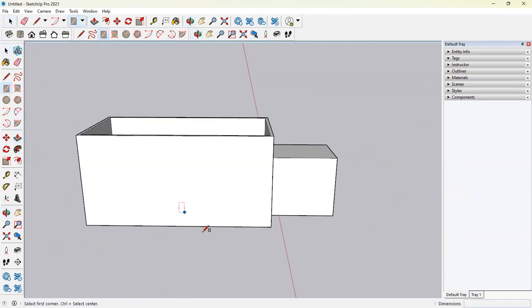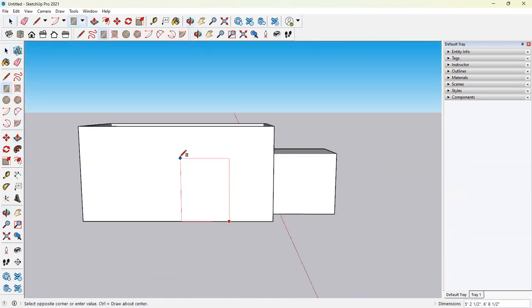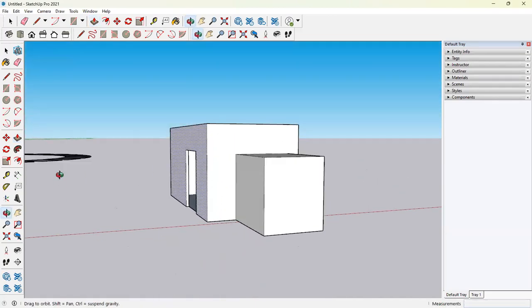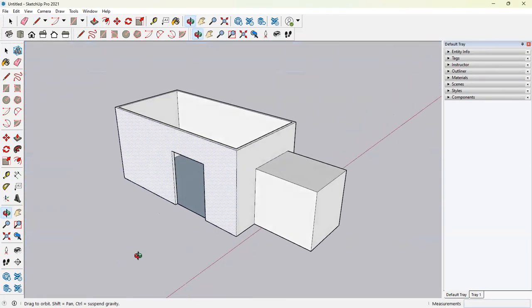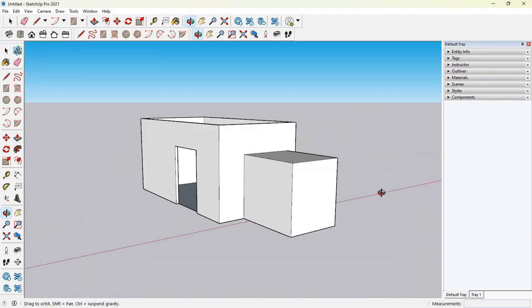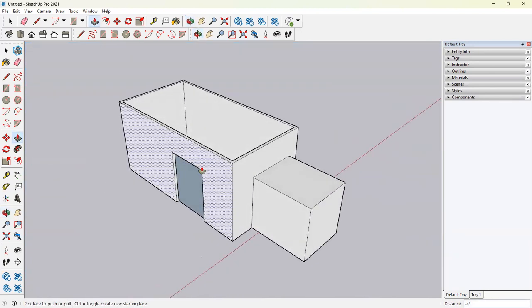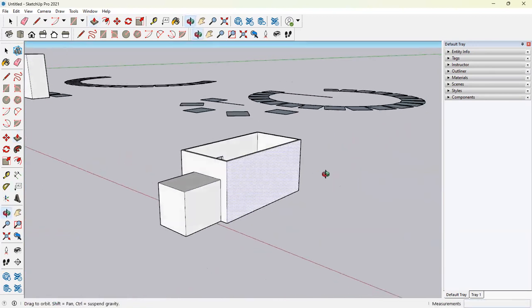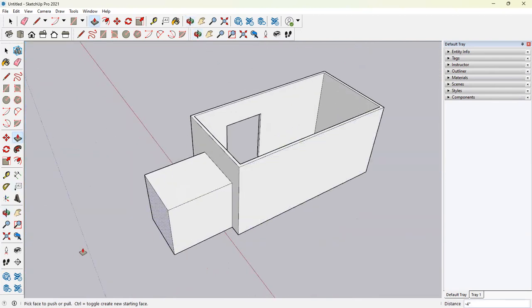Similarly, if I have a geometry here and I use push-pull, it's saying that its offset is limited to 4 inches because the thickness of our wall is 4 inches. So if you leave it, it will make a hole in the wall. So that is subtracting of the geometry. You can make doors, windows. This is the tool that we will be using for making walls, doors, windows, anything that has to be pulled and pushed, or creating geometries that are touching each other.